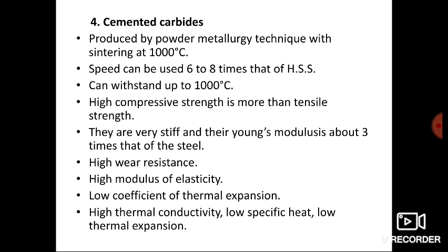It has high compressive strength compared to tensile strength, as it is made through powder metallurgy techniques. They are very stiff, and their Young's modulus is about 3 times that of steel. Again, it has high modulus of elasticity, high wear resistance, low coefficient of thermal expansion, high thermal conductivity, and low specific heat.